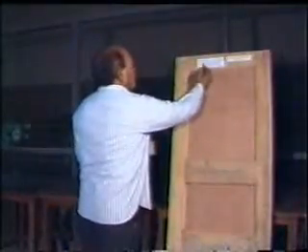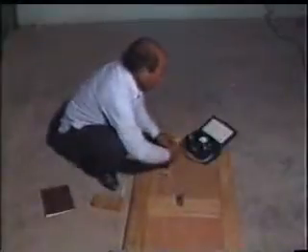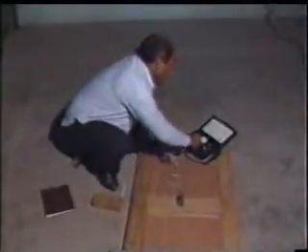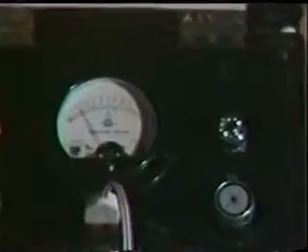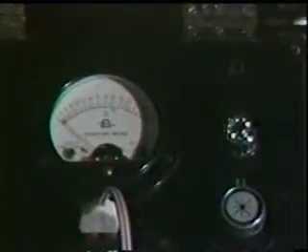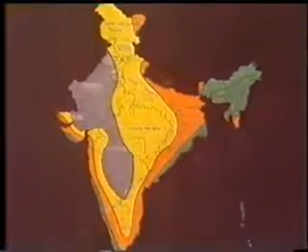Next, we come to the field tests. First, check the name of the manufacturer and any other identification marks as per supply order. Conduct moisture test on rails or stiles using moisture meter. Check that it is between 8 to 14% depending upon the region of the country due to various levels of humidity. The zones and maximum allowable moisture contents are as shown on the map.